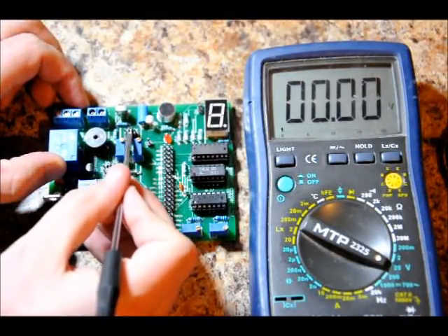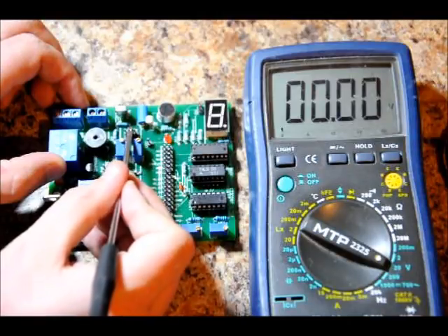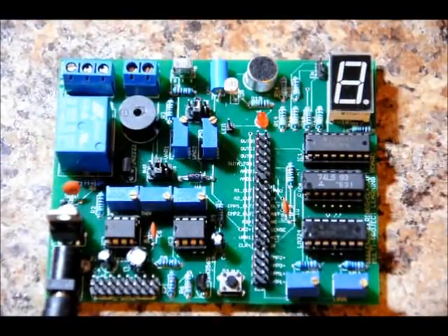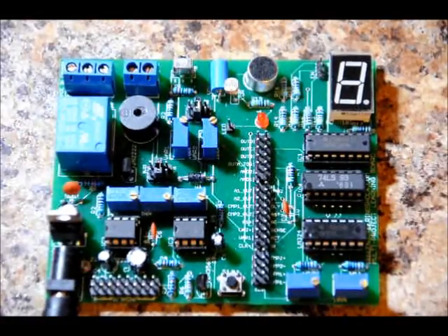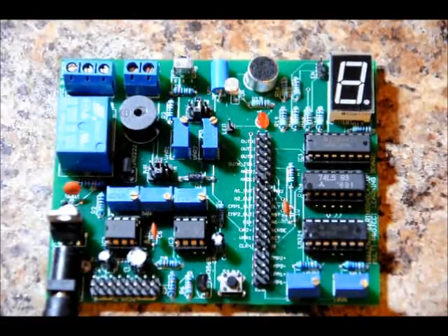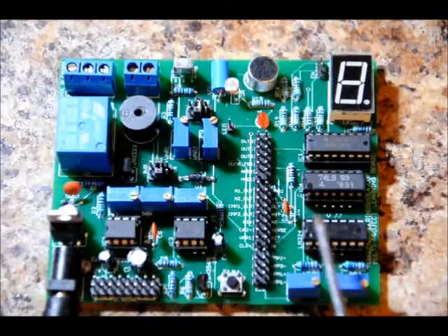Place the 2-pin header on the LDR pins. Okay. So what you can do, this is an optional step. I already know how the light-dependent resistor circuit is going to work. We just went over it. It's got a 10K resistor in series with the LDR circuit, and the sense line is in the middle. Now the sense line is right over here. It's labeled sense on the board.